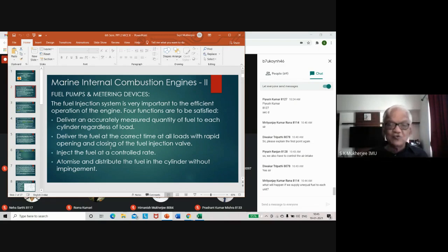So what they do is they have exhaust gas temperature dial gauges. They are not like thermometers. The dial gauges will indicate what is the exhaust gas temperature. And as a thumb rule, the best means to know how much power a unit is developing is determined by the amount of combustion that is taking place.